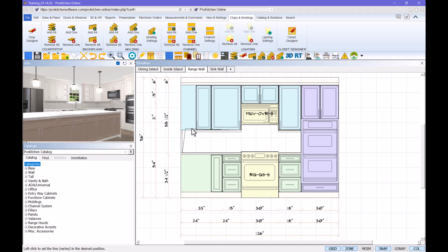from. This action will remove the section created at the intersection point and allow you to freely move the line on the remaining newly created shape. Once you have finished readjusting the shape, left-click to secure. The last of the four additional edit tools found on the lines is Radius End. This tool will add a curve to the selected line, creating a rounded edge to the shape.